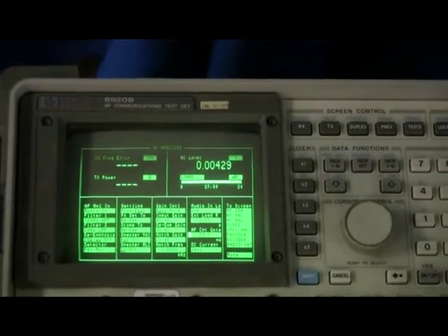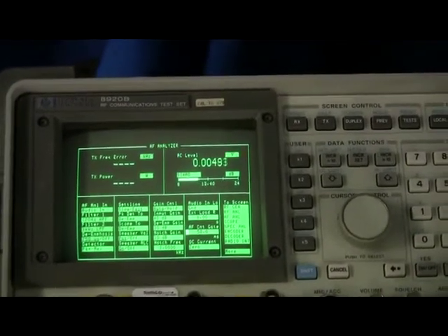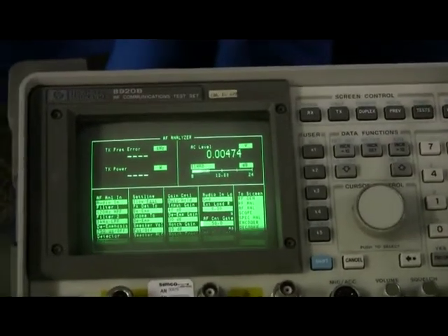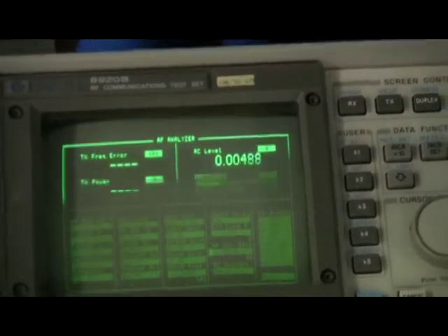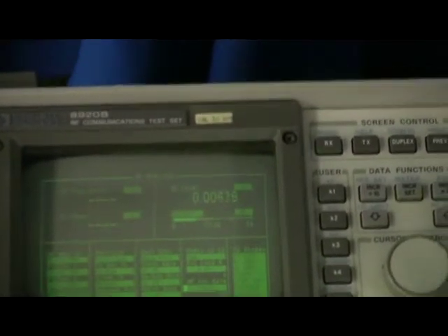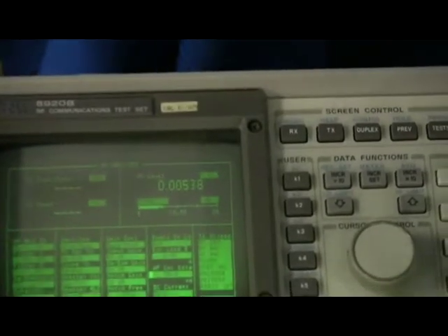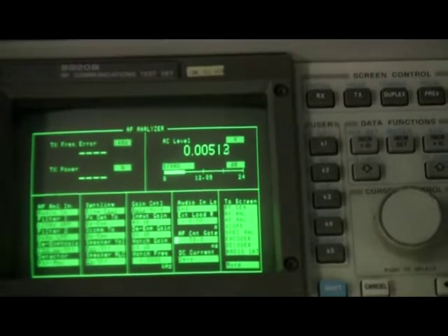So we'll add some attenuation to the uplink transmitter. I'm going to put in 20 dB of attenuation. And when I do that, we're at about the 12 dB level. I'm going to call that 12 dB. So for the case of no Cosite mitigation, we're able to attenuate the output of the uplink transmitter by 20 dB and still get acceptable audio quality from the system.